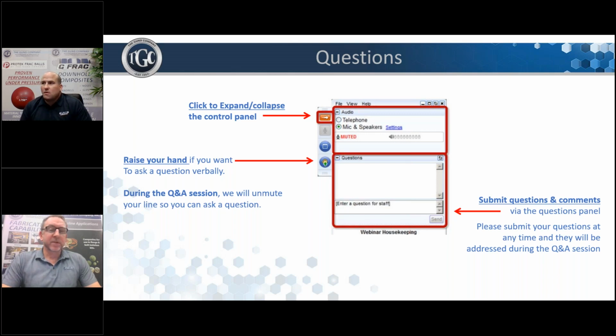And I will say the type of thread makes a big difference a lot of times in your success. We've found that there are a lot of different thread types that are more successful with composites, and you can't just use your standard thread type. And I think getting over 5,000 PSI can definitely be done, depending on the design, but a lot of it is going to depend upon the part density, what angles you're using, and what the function of the part is.